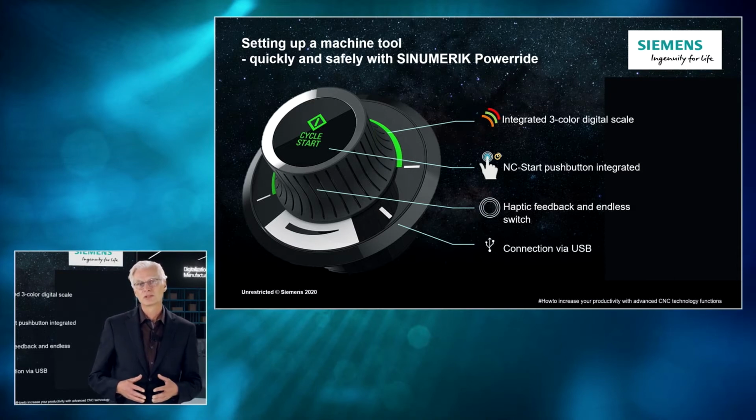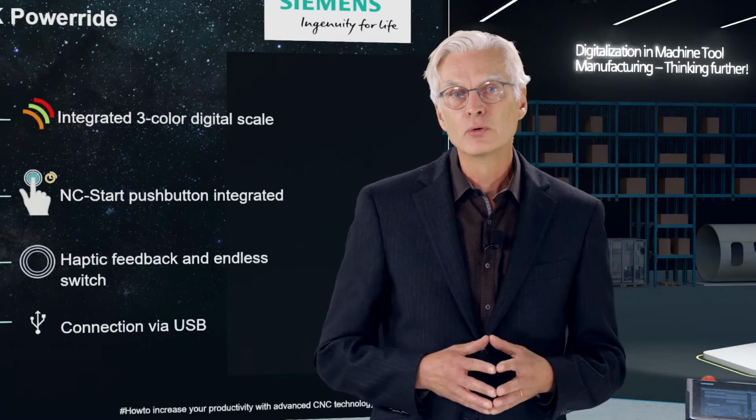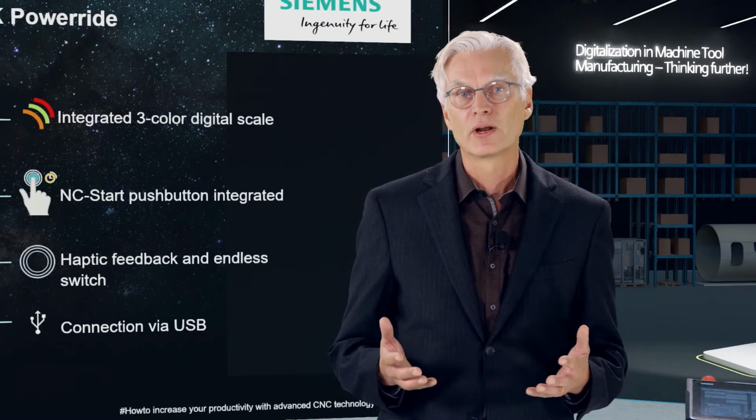Individual stop conditions can be specified by the user. This means that the CNC does not have to stop after each individual block, but only when the stop condition is met, for example, before a G0 block. This increases efficiency during setting up and reduces the risk of an unwanted crash.